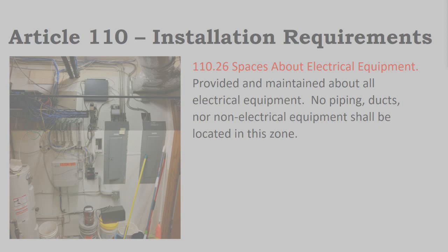And so just by looking at this room, this is a messy room, and there are also requirements to install your electrical equipment in a neat manner. And so we can see, say, this fiber optic networking equipment to the left of the service panels. That's not a code violation in the sense that it occupies the same working space of the panel. They're both electrical equipment.